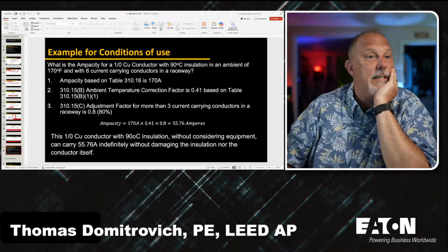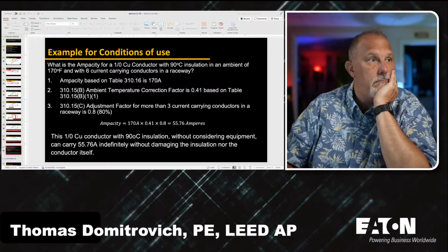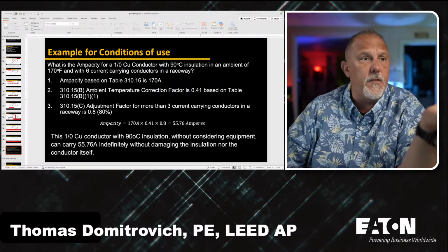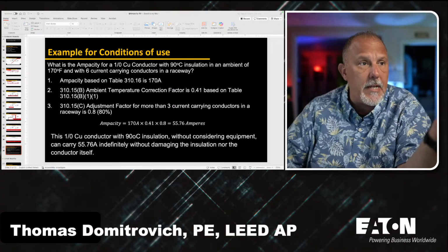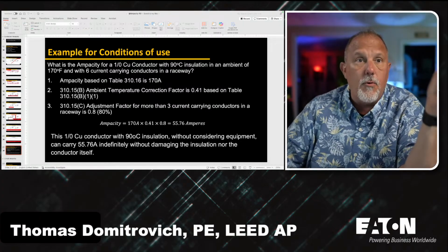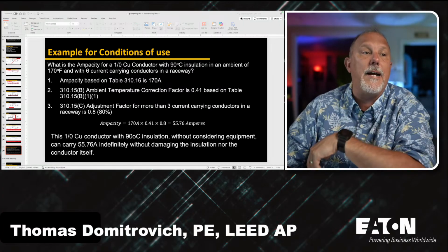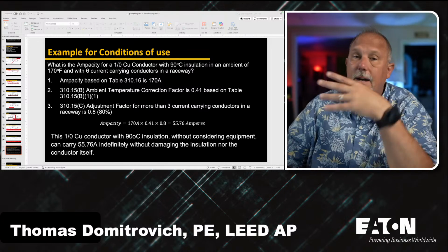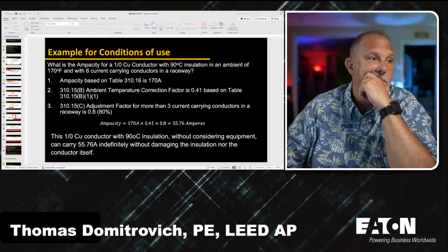I'm trying to think if I'm missing anything. I talked about the adjustment. Now it's not a roof. If it was a rooftop application and I was less than 3/4 of an inch away from the roof, I'd have to apply an additional factor. I don't have that, so I'm good.